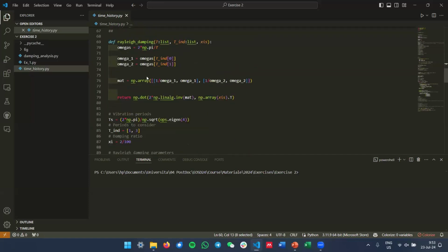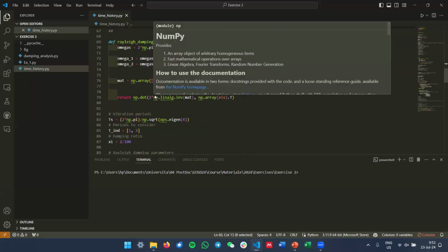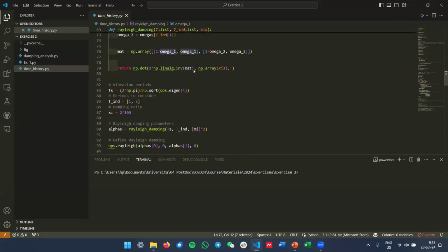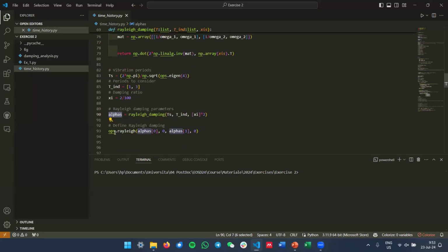I'm just declaring Rayleigh damping, as I showed you before. In this case, I just call them alphas here, but it's just alpha and beta, okay? The 2 parameters of Rayleigh that I showed you before, all the stuff. And I'm declaring here the initial stiffness, okay? 1, 2, 3, the third parameter, okay?